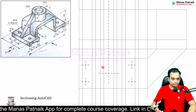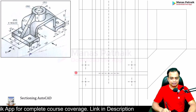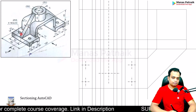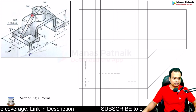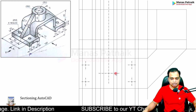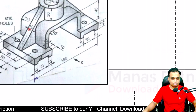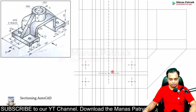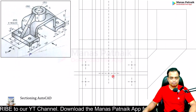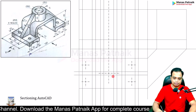Now, how do you proceed from here? What we can do is, we can make this rib. If you see carefully, this rib is passing through the center line. This is the center line I'm talking about. The width is 10. So 5 above, 5 below. Done. Rib work over.